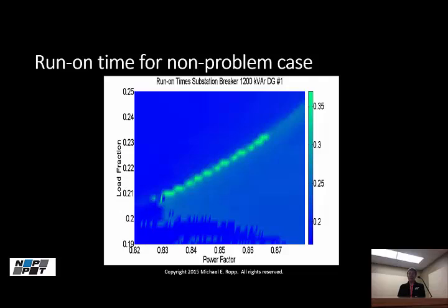And bear in mind that the IEEE 1547 recommended maximum run-on time is 2 seconds. So this is compliant. There's no problem here. No risk, no need for mitigation of a risk of unintentional islanding.